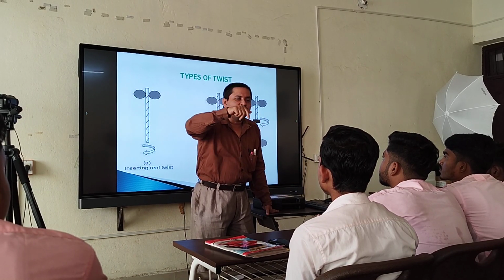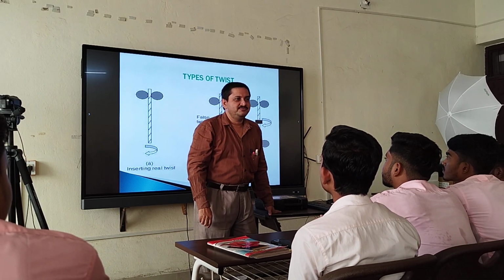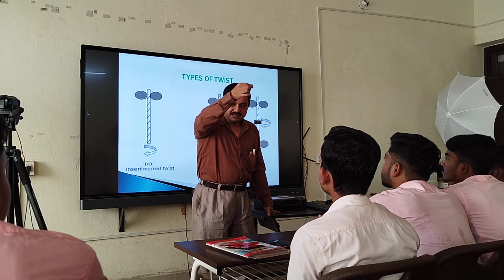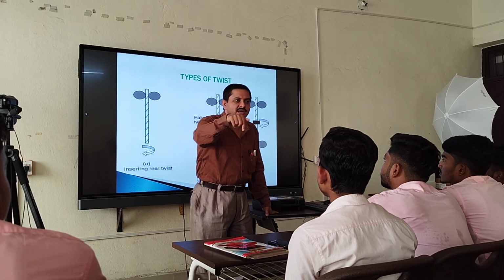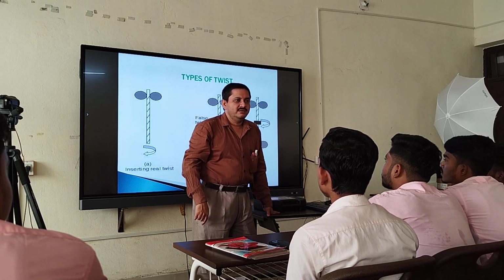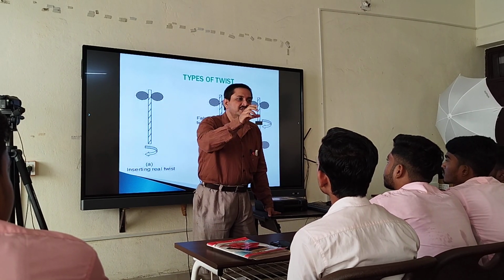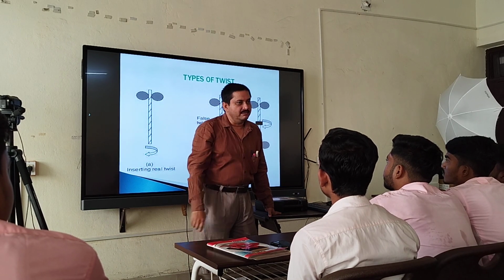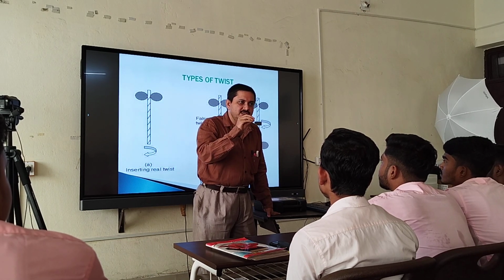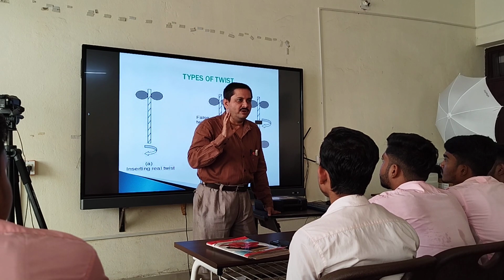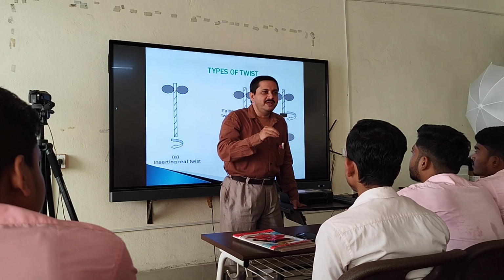But why should I apply it? What is the necessity of the false twist here? Because when the roving is coming out from the drafting zone towards the bobbin, if we do not apply this twist, ultimately disengagement or breakage of the roving takes place. And our target is to apply the twist to hold the fiber strand. Am I right? But practically, how much twist will be there within the roving?